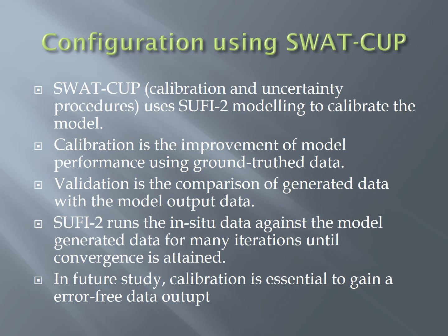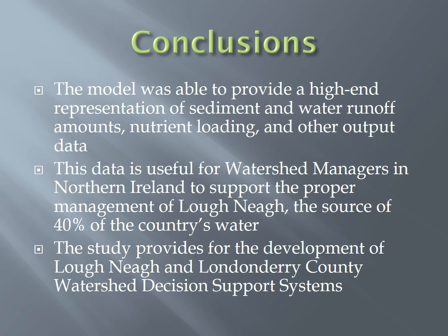Now, the next step for us was to run this model through SWAT-CUP so that auto calibration could be done and the model validation could be completed. As we know, SWAT-CUP uses the SUFI-2 approach to calibrate the model, and we did not have the actual data of the watershed. As I explained, Wyatt is doing his master's in Oxford, so he is in the process of collecting the actual results from the field. Then we can use the actual output to run SWAT-CUP so that the model can be calibrated well, and the final result will be validated with the field data that Wyatt is collecting. So that's our project.